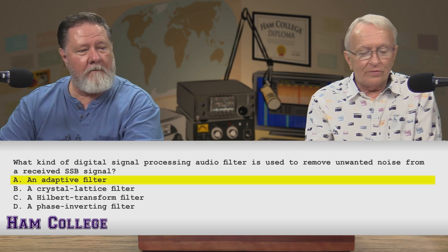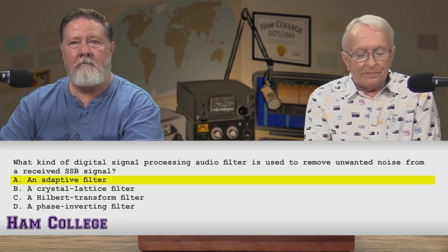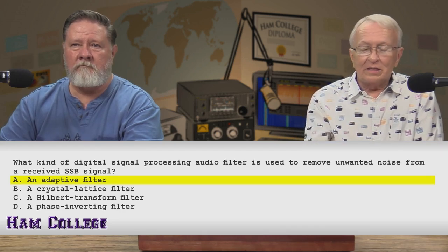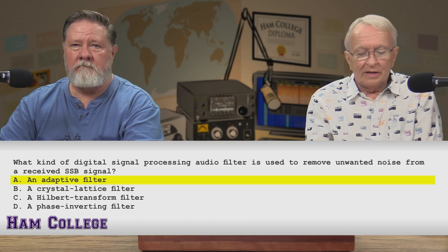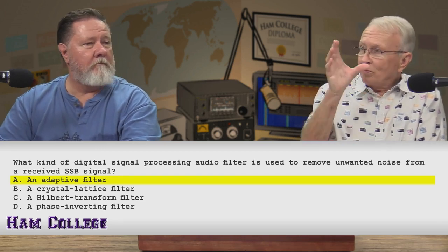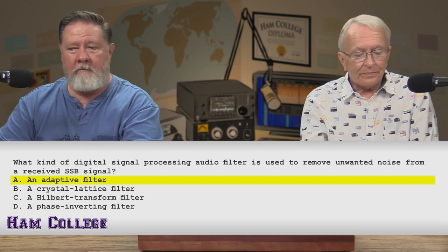And the exact frequency of the power and the harmonics may vary from moment to moment. So you can't say that we're just going to put a 60 hertz notch filter in there and that's going to exactly remove it. It would help, but it's also going to remove part of the heartbeat signal as well.